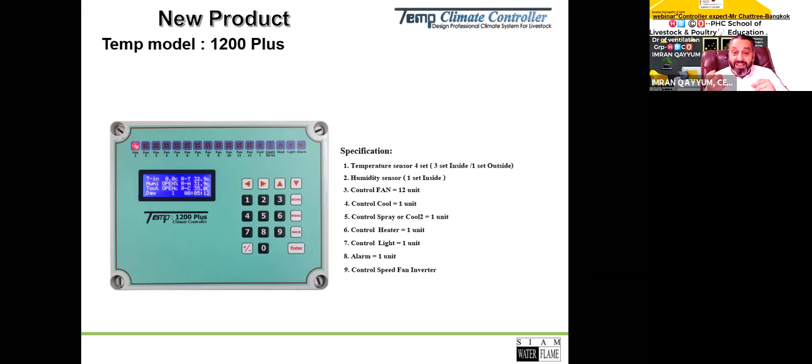Dust is the main problem. The diaphragm of the pressure sensor is disturbed by the dust, and the reading is also disturbed, with some difference in the reading because of the dust.